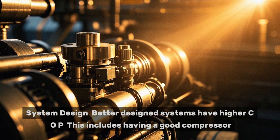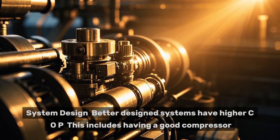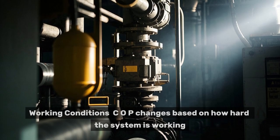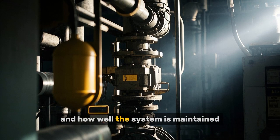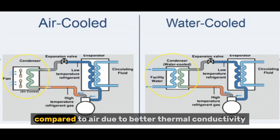System design. Better designed systems have higher COP. This includes having a good compressor, accurately sized heat exchangers, and the right refrigerant. Working conditions. COP changes based on how hard the system is working, the outside temperature, and how well the system is maintained. Medium used. Using water as a cooling medium can improve COP compared to air due to better thermal conductivity.